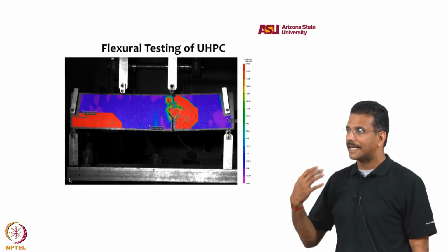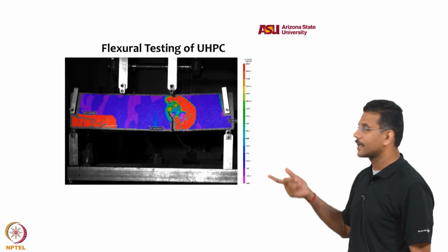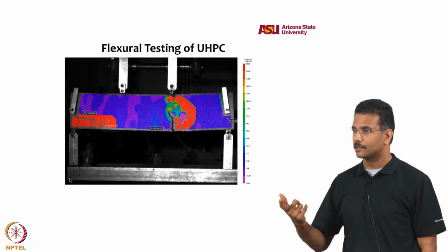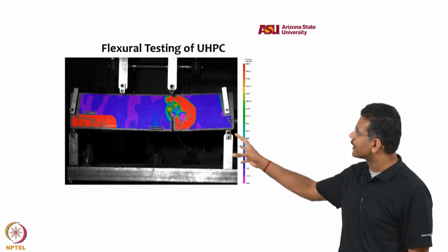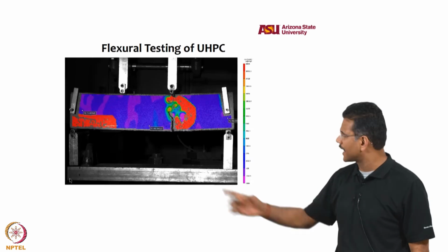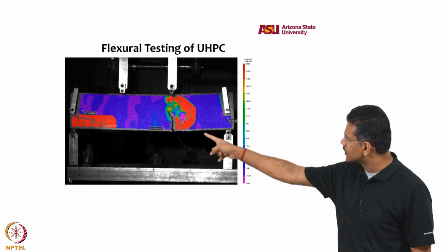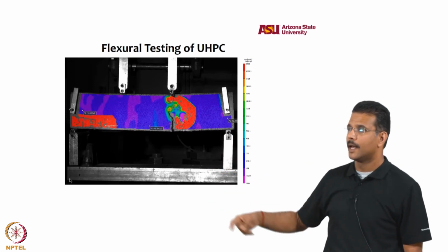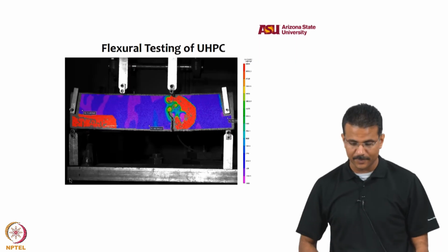If you theoretically calculate the process zone as some value of strain, you can actually quantify what the process zone is and how it changes with load. You will see random cracking, and extremely high strains at different locations. Now, you can see this again at the edges, but I would not consider those artifacts. If I just zoom into the portion under the load, I can start to understand how a crack actually propagates in these materials.